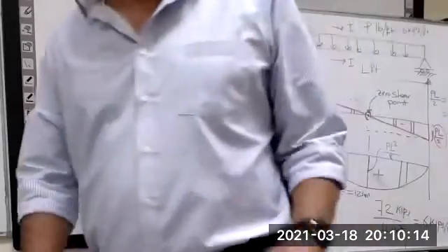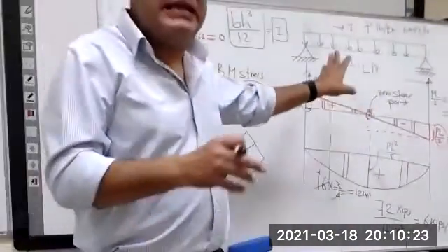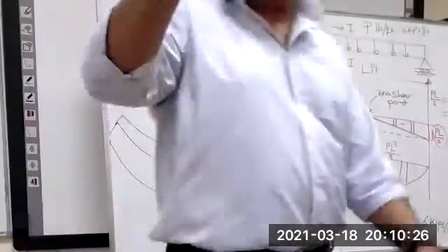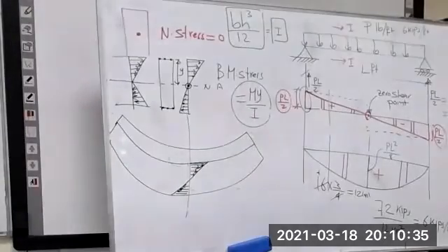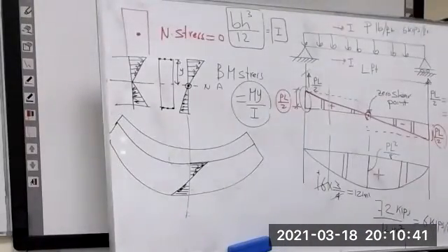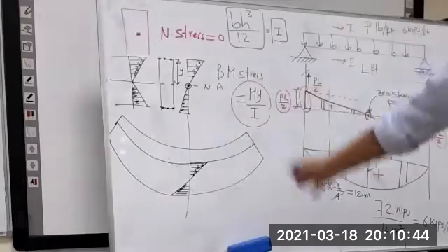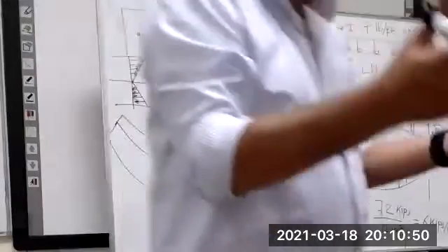But what if, instead of uniform load, they use point load? Then what would be the answer? If the condition changes, it is different. If any condition depends on the external forces, I am just giving you the same one, with uniform load. If we have a concentrated load, calculate the shear, calculate the moment, and in the end apply the formula. Simple. It will not come to you as a concentrated load, but if it does, you have the formula, the steps, the mechanism. Everything is in your hand now.